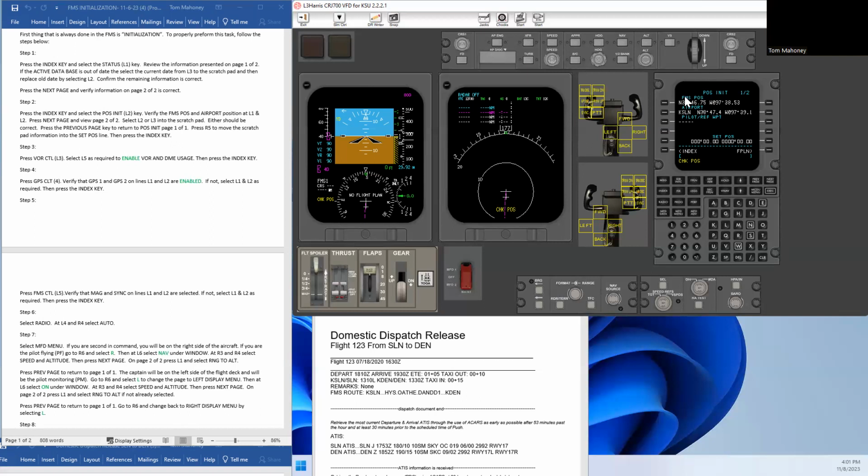I take note of the lat longs in L1. I verify that they are something close to what the Salina airport says. That's not going to be exact unless we have the aircraft parked exactly at this location. It's probably not; it's parked at some gates. So they aren't going to match exactly, but they're going to be close.